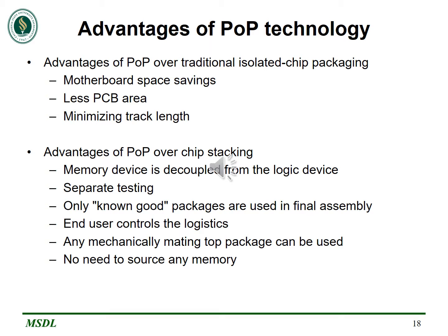This means memory from different suppliers can be used at different times without changing the logic. The memory becomes a commodity to be sourced from the lowest cost supplier. This trait is also a benefit to package in package, which requires a specific memory device to be designed in and sourced upstream of the end user. Any mechanically matching top package can be used.